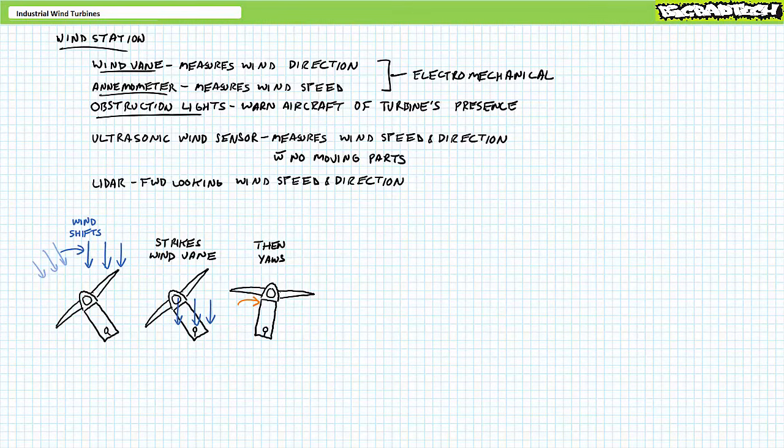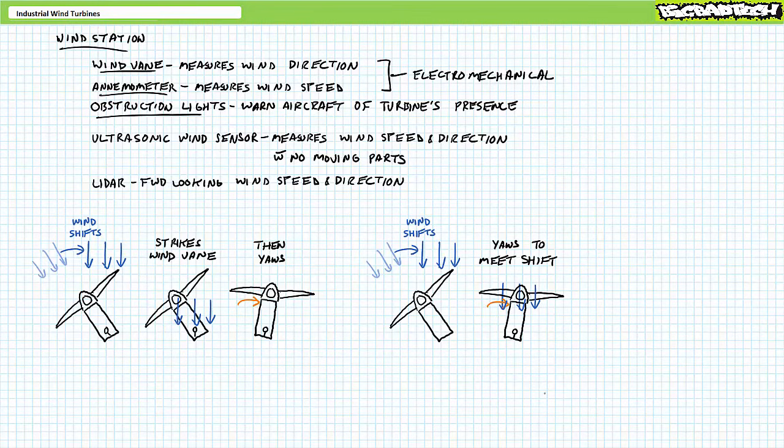For this reason, some manufacturers are researching forward-looking wind speed measurements using LiDAR. These types of sensors can sense a change of wind speed or direction well in advance of it actually striking the turbine, and the controller can take proactive means of responding to this impending change by adjusting yaw position or blade pitch in advance, such that the turbine meets the wind head-on and efficiency remains high and mechanical stress remains low.